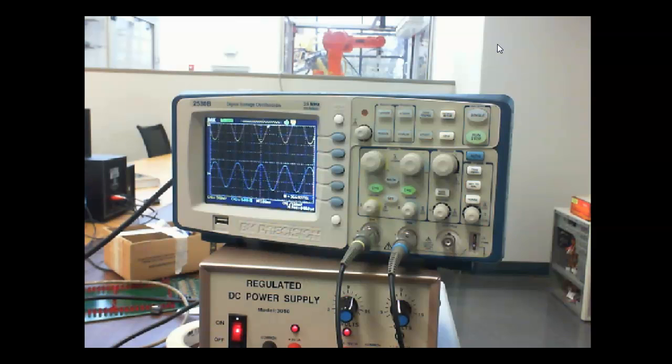So you can hook them in parallel, or hook them up in series, to try to maintain pretty close to 2 ohms on your stereo, right? Most of them have a little range on that. House speakers are 8 ohm speakers. So if you take a house speaker and put it on your car radio, you're going to get crummy sound too. Why? Because you screwed up your impedance matching, right? So now you understand that kind of stuff.